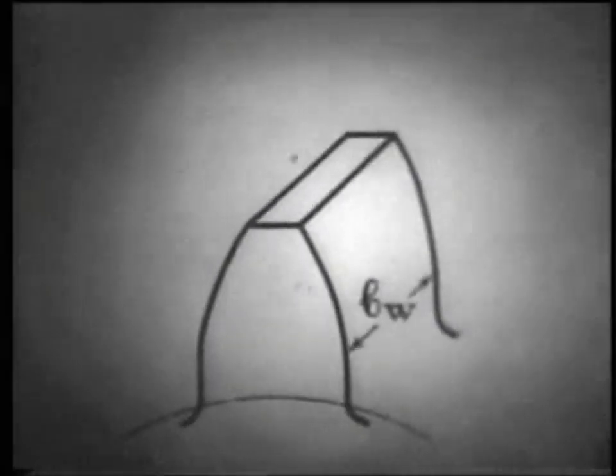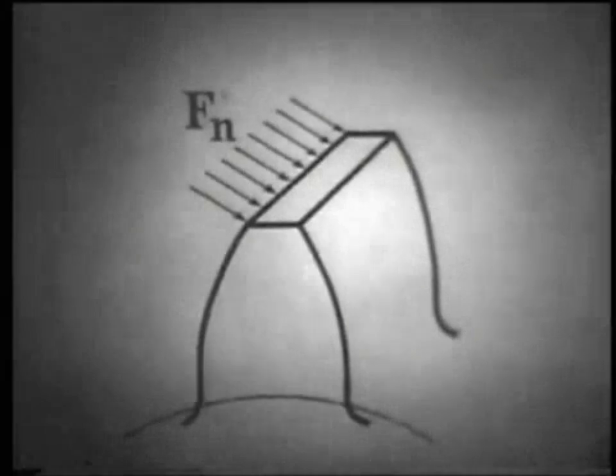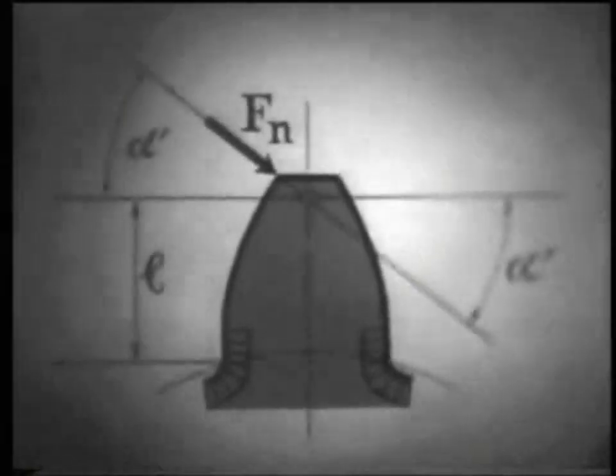In addition to calculating the contact strength, it is necessary to check the tooth for bending endurance. In polarized light, it is clearly visible that it is at the foot of the tooth in the loaded transmission that the maximum stress occurs. In the presence of significant errors of the base pitch, the entire load is applied to the edge of the tooth. This is the worst case.